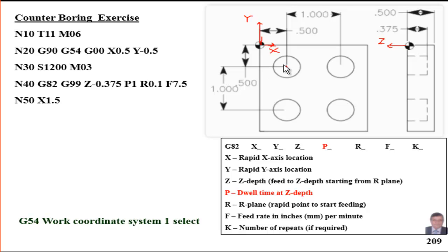What is next is to move the tool to that position. Once we finish hole number 1 and number 2, we go for number 3. So what change do we make here? X will be the same, so no change in X. We are concerned about the value of Y. What is the value of Y?